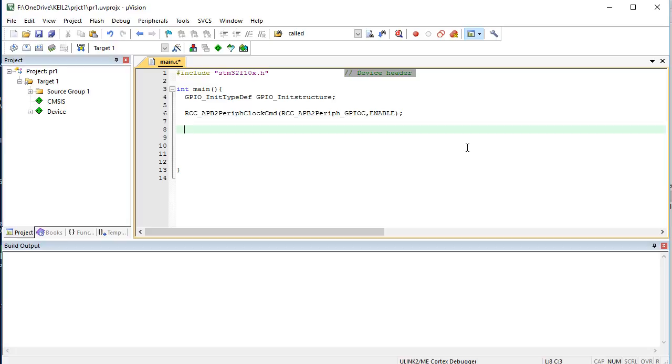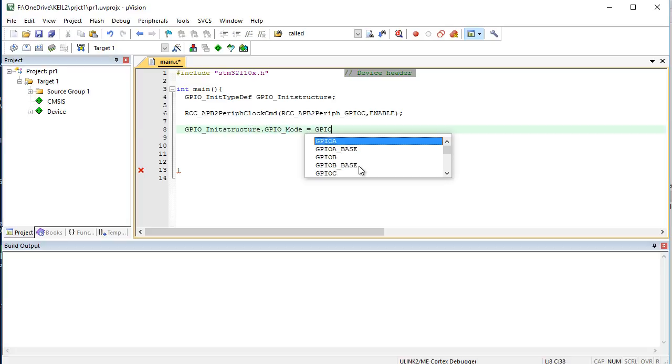After that, we need to initialize our output modes. So we go to the GPIO init structure we defined before, about two lines up, and GPIO mode. It already gives you hints. So when we type GPIO mode, we type GPIO mode again. We want it to be output, so we can blink the LED. So I will make it push-pull. I believe you already know what push-pull is.